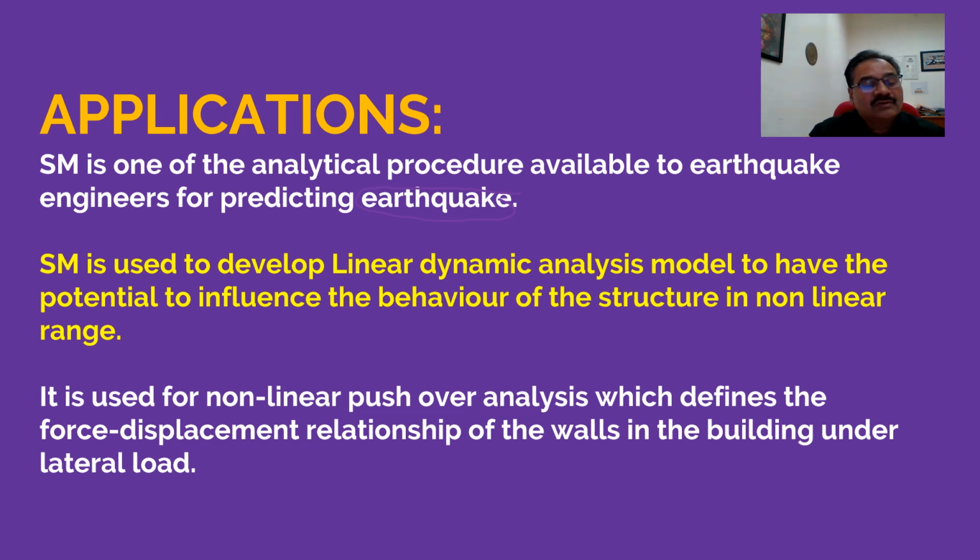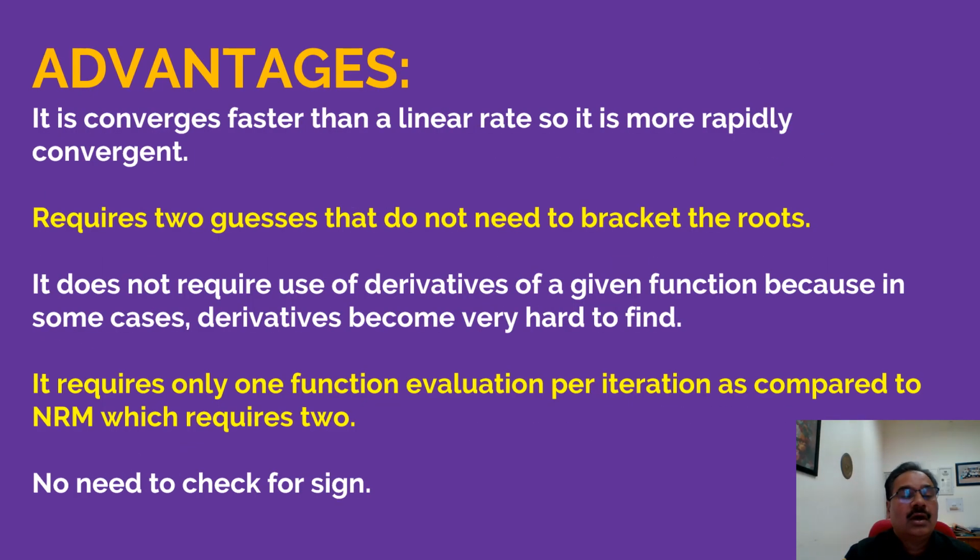The secant method is used to develop linear dynamical analysis model to have the potential to influence the behavior of the structure in non-linear range. It is also used for non-linear pushover analysis, which defines the force displacement relationship of the walls in the building lateral load. Okay, so here also we use the secant method.